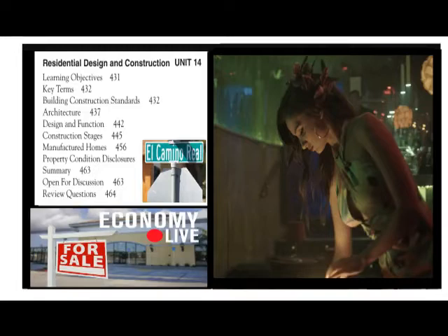The sill is the wood member that is placed directly on the foundation wall. Since 1931, California building codes have required the use of anchor bolts through the sill and into the foundation wall as an earthquake safety measure. Nevertheless, the California legislature has estimated that 1.2 million homes in the state have foundations that are not adequately secured. Government Code 8897.